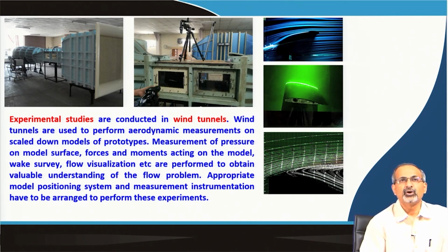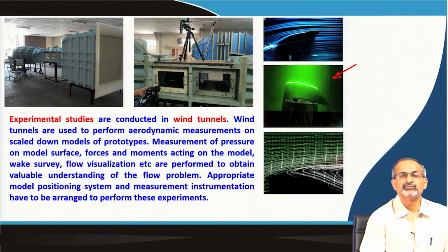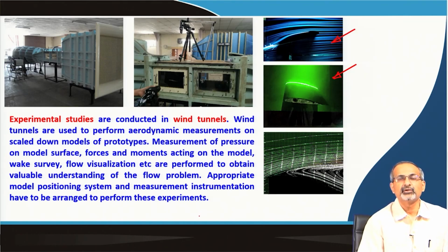So, in the last few modules we have discussed quite a few measurement techniques. Now the point has come where we are talking about a laser based technique, the particle image velocimetry technique. In this wind tunnel we had discussed how a smoke flow visualization, for example, would look. That gave us very useful qualitative information, but if you want quantitative information, then you have to have a measurement technique like particle image velocimetry, which again is not confined to single point measurement. You can have the measurement done for a particular region of the space, a region of interest to you.